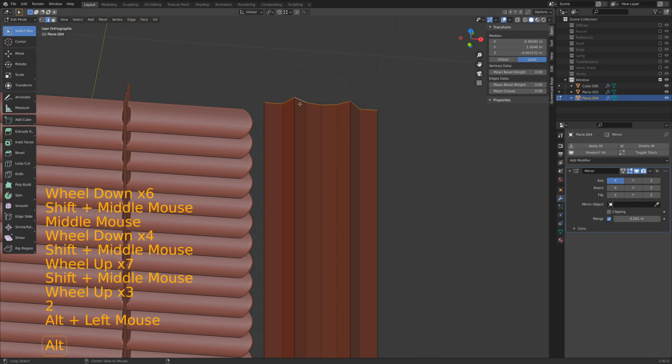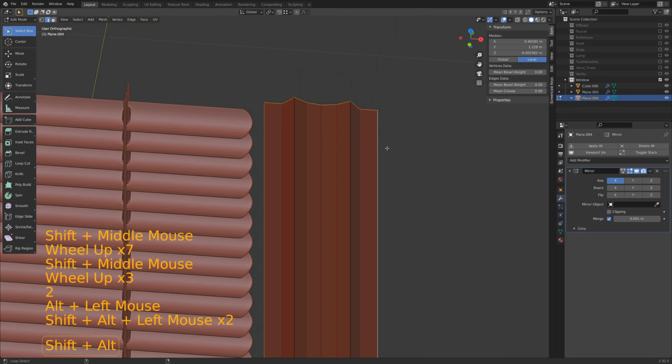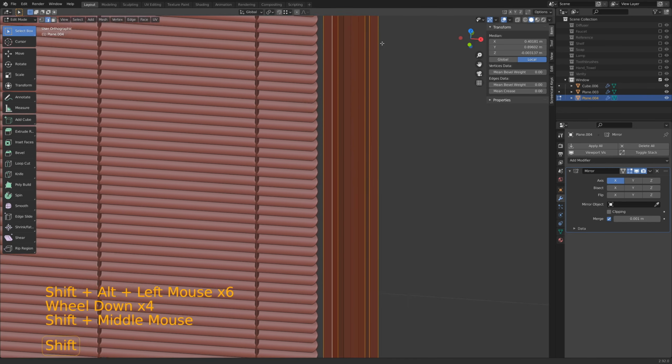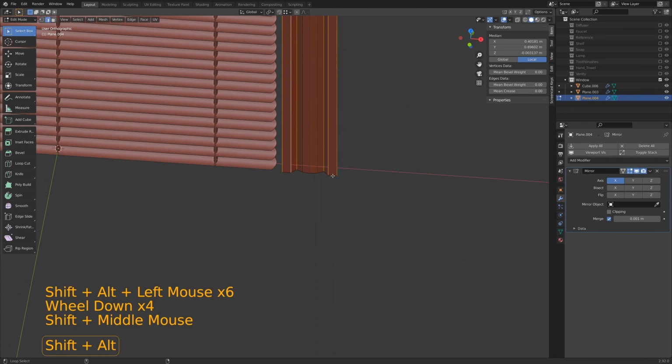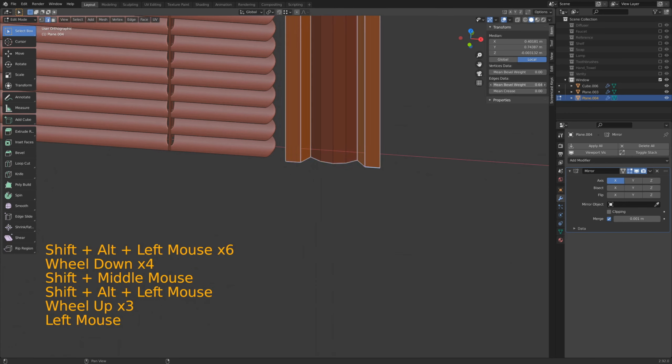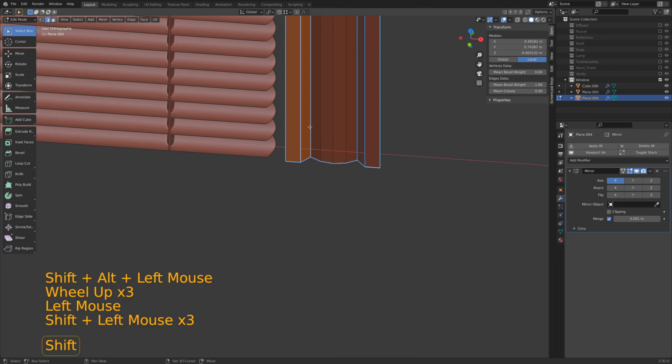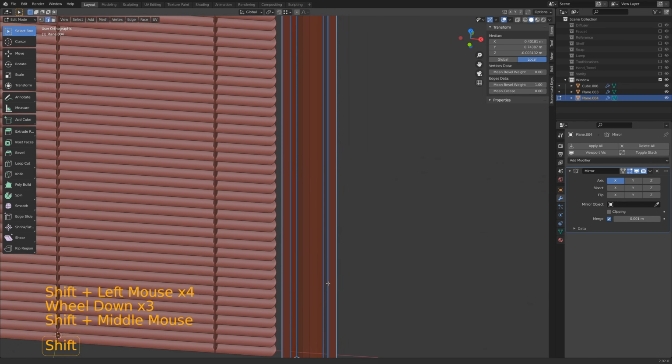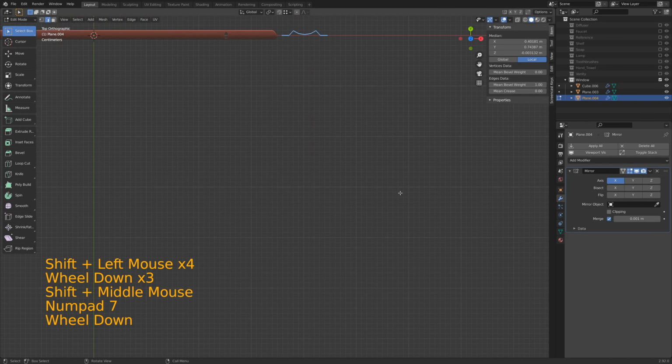Now let's take all of our edge faces as well, as these are going to have to be beveled. We're going to use a bevel modifier to do that, so let's just mark them. And now only select the border faces.